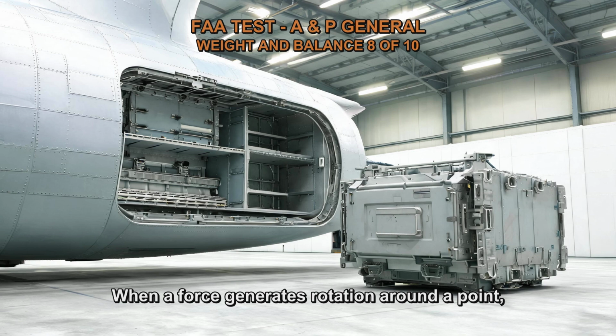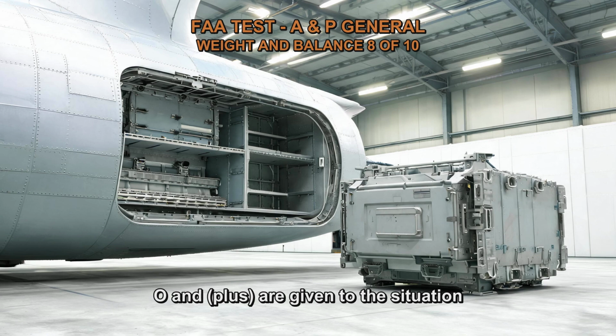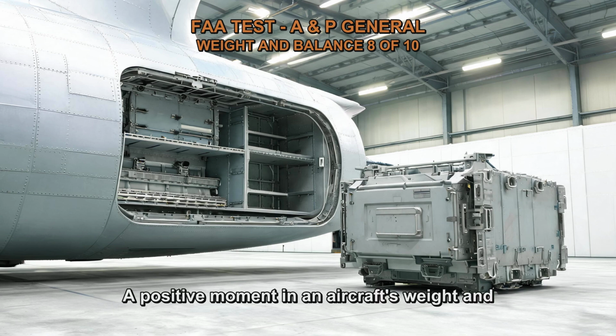When a force generates rotation around a point, it is known as a moment, and signs are used to indicate the rotation's direction. Minus and plus are given to the situation at hand. A positive moment in an aircraft's weight and balance is one that causes the nose to rise, and a negative moment is one that causes the nose to descend. We have 4 options for the sign of the moment because a moment is the product of weight and distance from the datum, both of which are signed values.